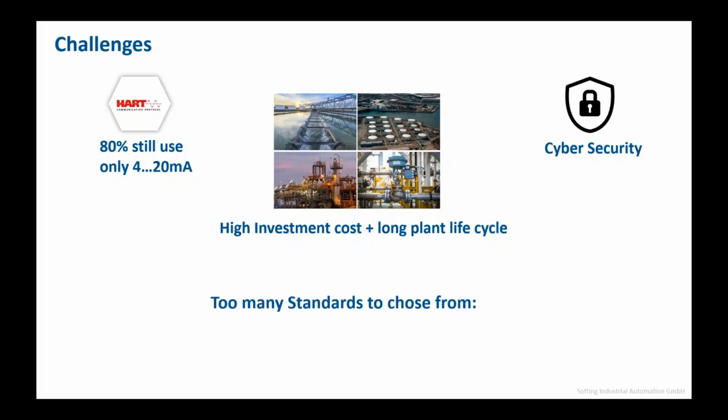But the hardest challenge of all of them is that I have too many standards to choose from. We don't know which one fits my application best. We don't know which one is supported by my usual supplier. So it can be that I want to have, let's say, Foundation Fieldbus, and my supplier doesn't support Foundation Fieldbus. He only supports Profibus PA. That's also a big challenge that we have to handle and maybe plan in a different way.